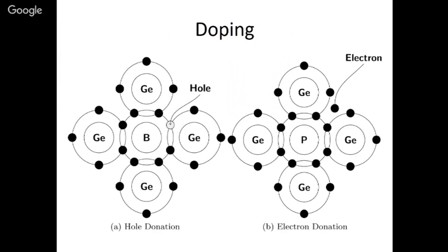So doping. What is doping? In this case, what we do, we just add impurities to silicon or germanium. You know, mostly the base of this PN junction, diodes or semiconductor devices, either silicon or germanium, whose valency is 4. Valency electrons are 4. So in this case, here you can see germanium is used, and this germanium, it has 4 electrons, and now you are adding an impurity which is boron to it.